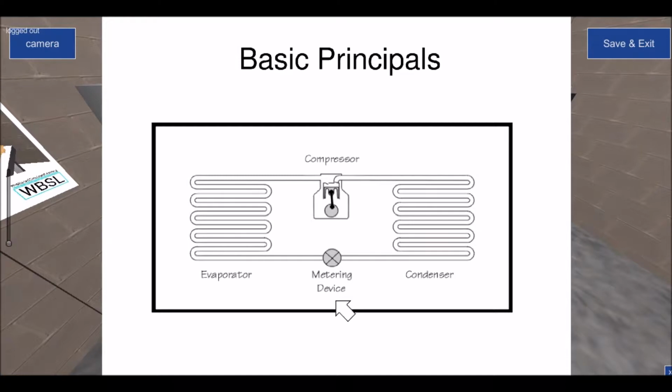What I mean by that is, for example, we have a compressor, and the compressor's primary function is to take low pressure, low temperature superheated vapor, drawing it from the evaporator, and compress it to a high temperature, high pressure superheated vapor, and discharge it into the condenser. So it continues to suck and pump, pumping the refrigerant around the enclosed system.